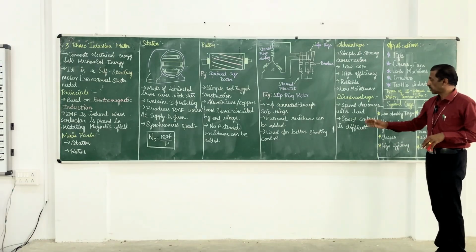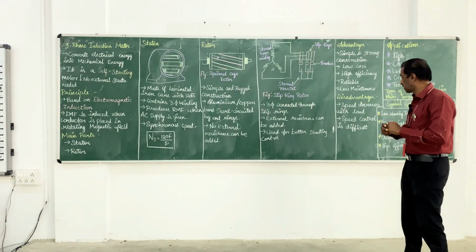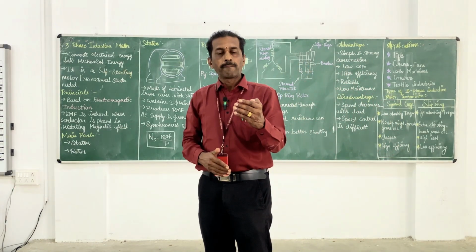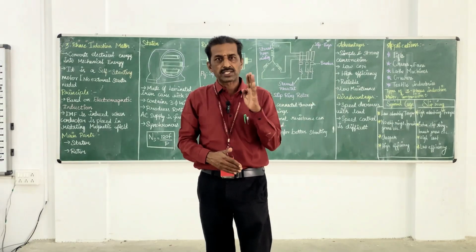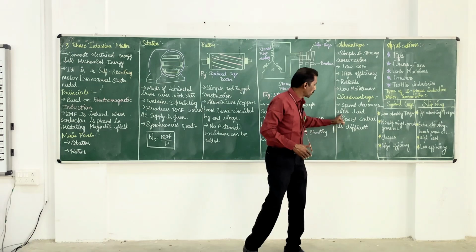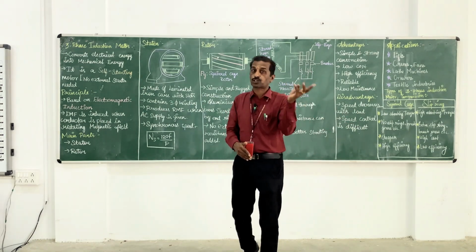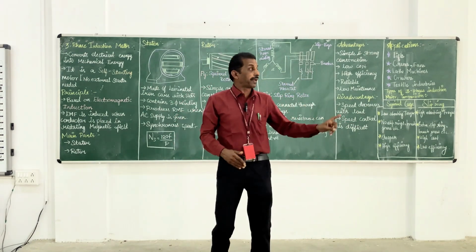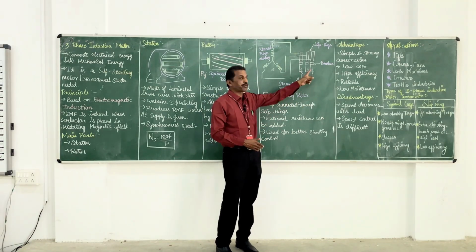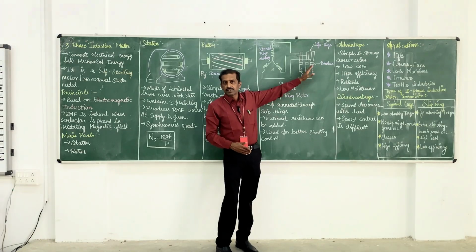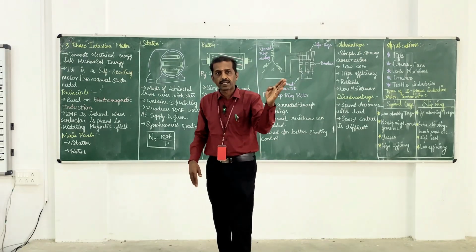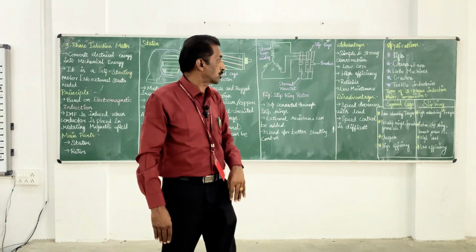Disadvantages: speed control is very difficult, and the speed does not attain the synchronous speed. In any condition, the synchronous speed Ns is not equal to Nr. The second one is that speed control is also very difficult for the squirrel cage induction motor, but the slip ring induction motor makes speed control possible, because we connect external resistance. Whenever the external resistance is changed, the resistance value may increase or decrease, and at that time the torque will change almost accordingly.